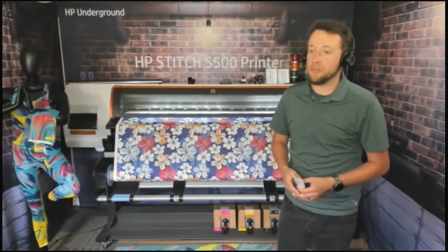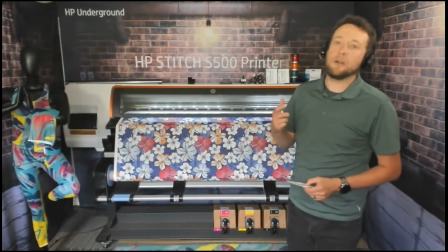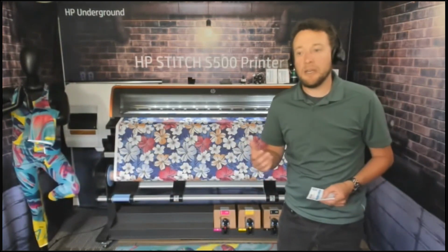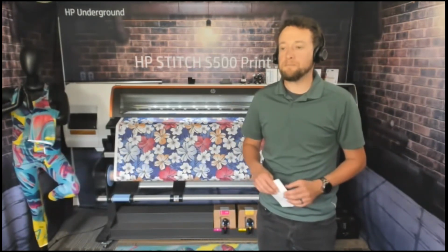So I think for me, I've covered the gamut here on the printer. Just to recap, we talked about the differences between contone and halftone. We also talked about the differences between Piezo Printhead versus Thermal Inkjet Printhead. I also walked you guys through the technologies of the printer, with the printhead, the drop and dry prints on dryer, the nozzle compensation system and the optical drop detector, and even the spectrophotometer that is on this printer. First dye sub printer to have the spectrophotometer as well.